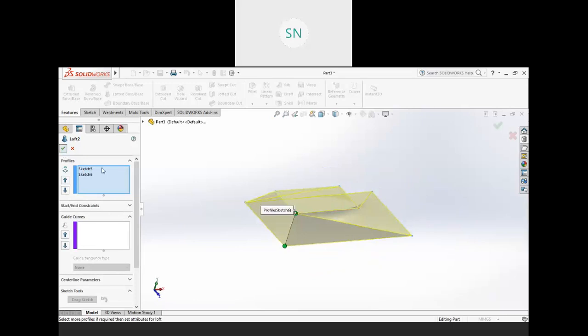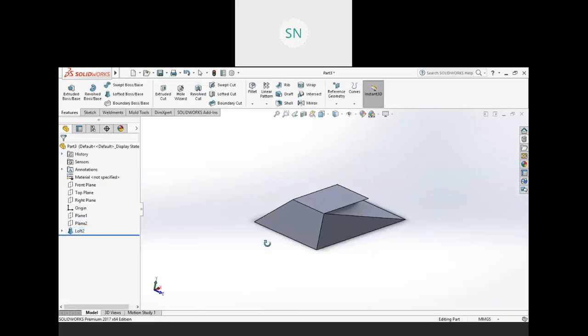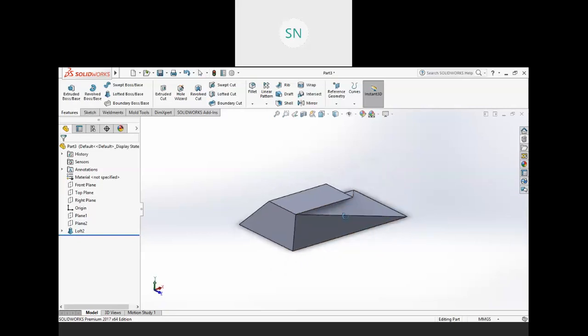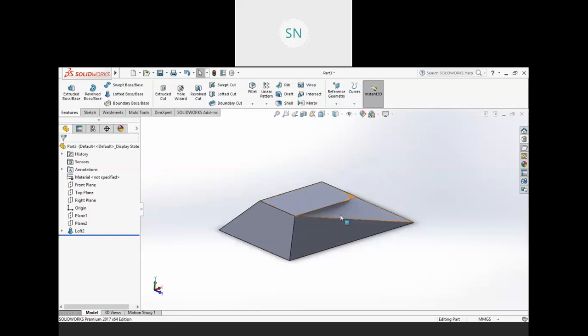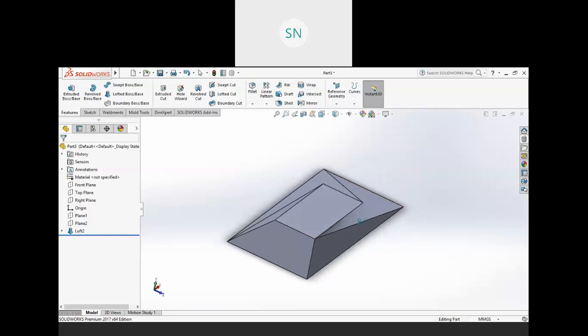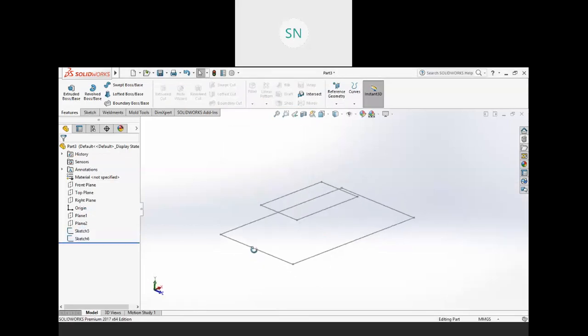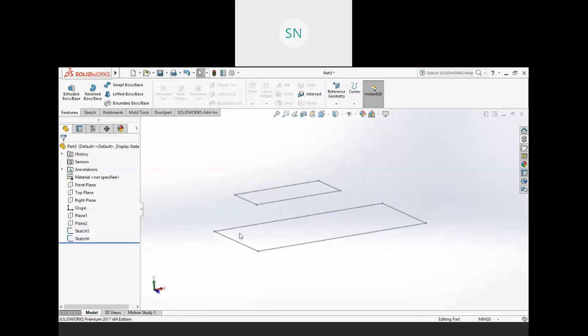So you will mismatch your geometry like this. So before you finish, make sure each and everything is fine, then finish your geometry. Then next we have some guide curves. So I hope you are clear about the twisting profile.